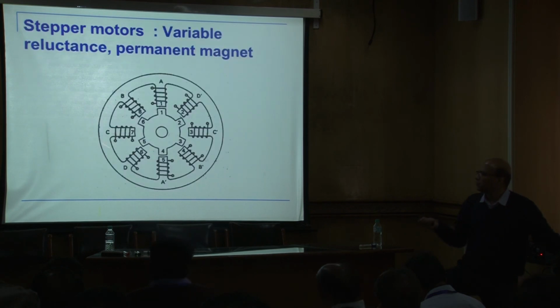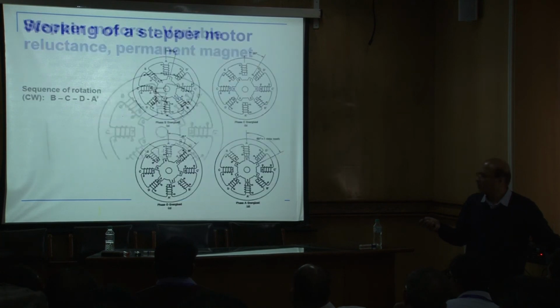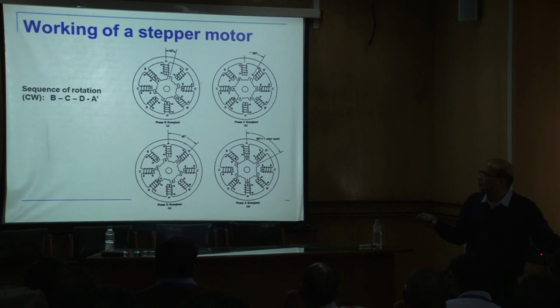So stepper motor, you would have again studied this. Essentially, it works in steps. So we have a stator and we have a rotor. Depending on how we are actuating this, if I actuate this pole, what would happen? This fellow will get attracted by magnetic induction. So there is a permanent magnet stepper motor in which if we actuate this one, this will get attracted. Then if I actuate this one, this will get attracted. If I actuate this one, this will get attracted. Based on that, it can move in a clockwise, anti-clockwise direction simply by sequencing the activation of the pole. So this also experiment we have, which you'll have to do, write a program and then use microcontroller